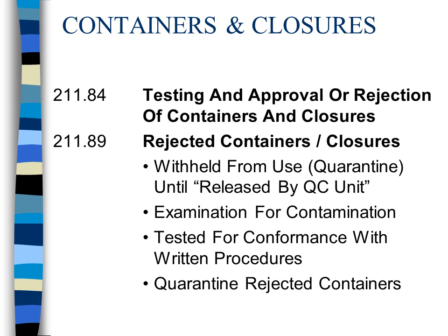The testing and approval or rejection of the containers and closures, again, as a driver, when you are in the process of filling a liquid nitrogen dewar or a liquid oxygen reservoir, one of the first things you will do is a visual inspection. If you find that you cannot fill that because the vessel that you're trying to fill has maybe a gouge, a large dent, dirt, grease, or any other contaminant, you contact your QCU member.